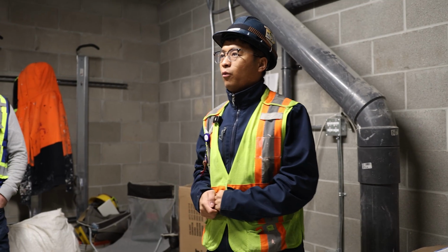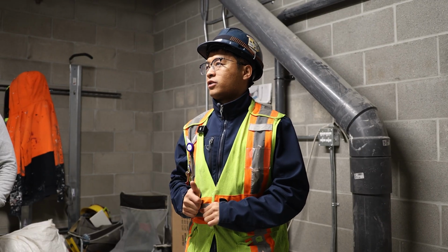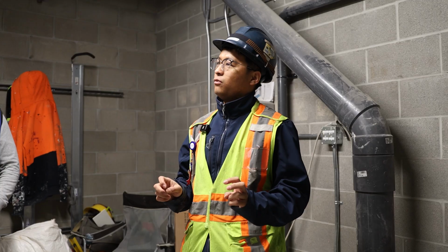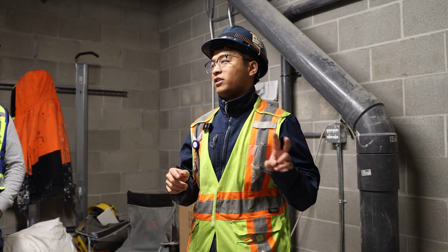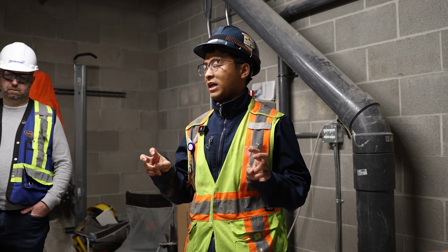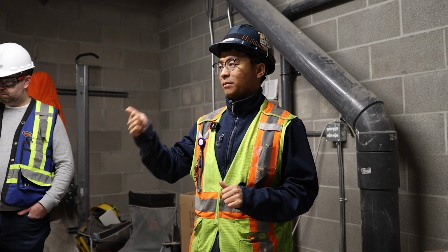So we have two space temperature sensors in the laundry room. So it doesn't have winter mode or summer mode. It just runs. What happens is the BMS monitors those two stats, and we also have a set point for those thermostats. And the make-up air unit turns on to maintain the supply temperature.